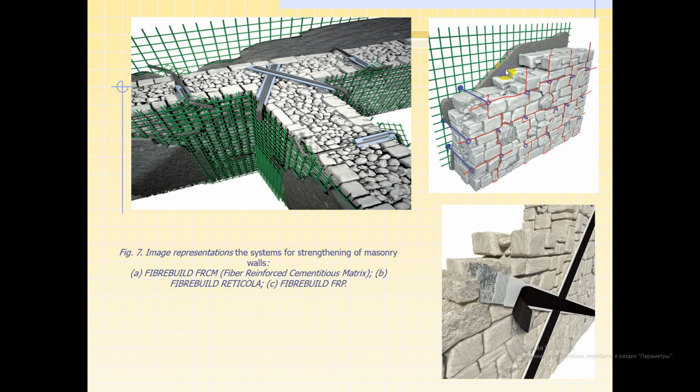Reinforced repointing method, where stainless steel cord connections are used to consolidate exposed stone masonry. The system helps reinforce masonry diffusely and successfully while preserving the original look.